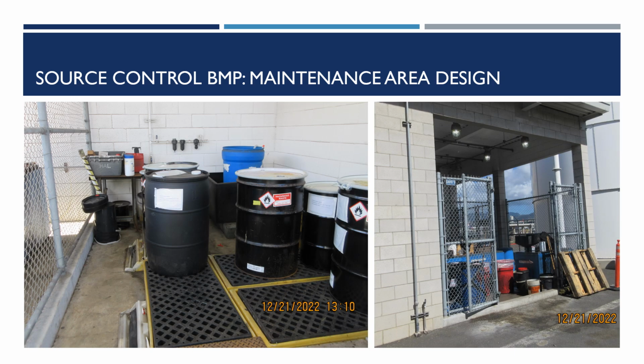Material storage area design involves incorporating design criteria for material storage activities. Considerations include secondary containment structures, designing outdoor storage areas to be covered, or designing them to preclude stormwater run-on and run-off, and routing downspouts such that runoff will not flow through material storage areas.